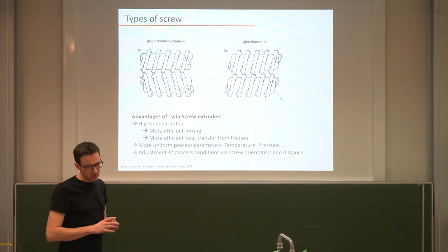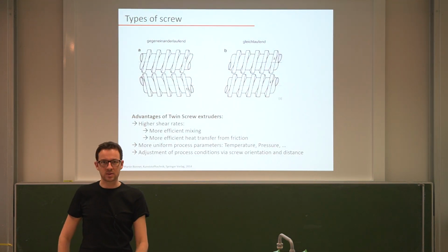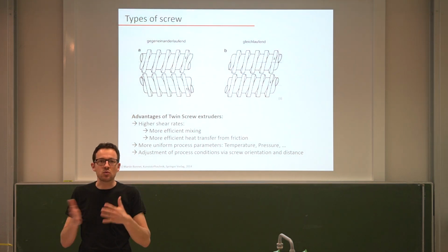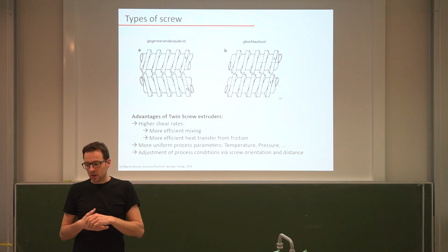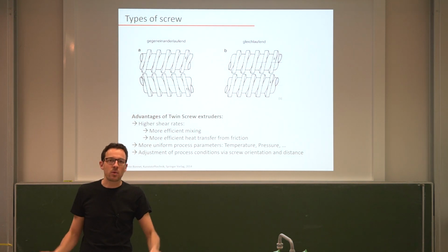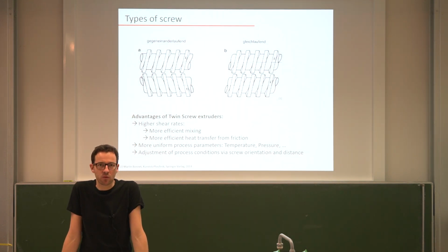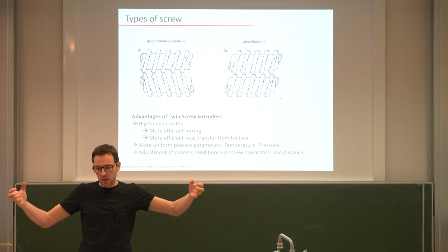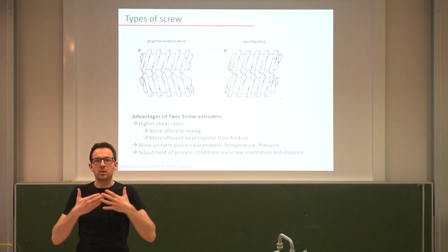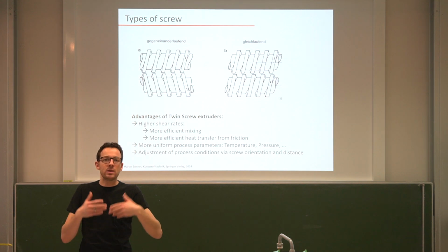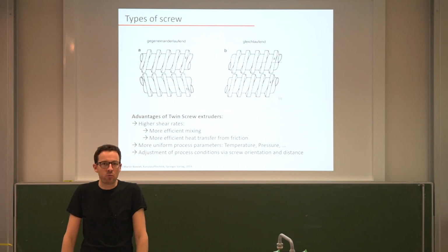Now, of course, there are a lot of different polymers, and we discussed this at length, that the glass transition temperature of the polymer, or if you want, the resistance to polymer chain movement, can vary dramatically. Think about the difference between a very soft rubber, polyisoprene for example, and something very hard, like Kevlar, if you want to go to the extremes, that literally doesn't melt at all and is very stiff and shock absorbing. And of course, in your extrusion process, you need to accommodate all these different types of thermal behaviors of polymers.